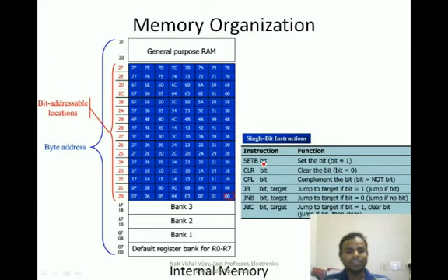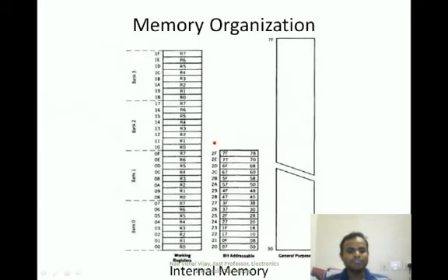as we can see at my right, using some instruction like set bit. The bit can be any one of these address locations, you can say 20.00, 20.01, 20.02. It will set or clear or complement or jump on a bit. It depends upon the bit addressable instruction. You can access a particular bit in the bit addressable area in 8051. Apart from these bit addressable locations, the remaining locations are covered by your general purpose registers, that is from 30 to 7F, which can only be accessed by their memory location address.